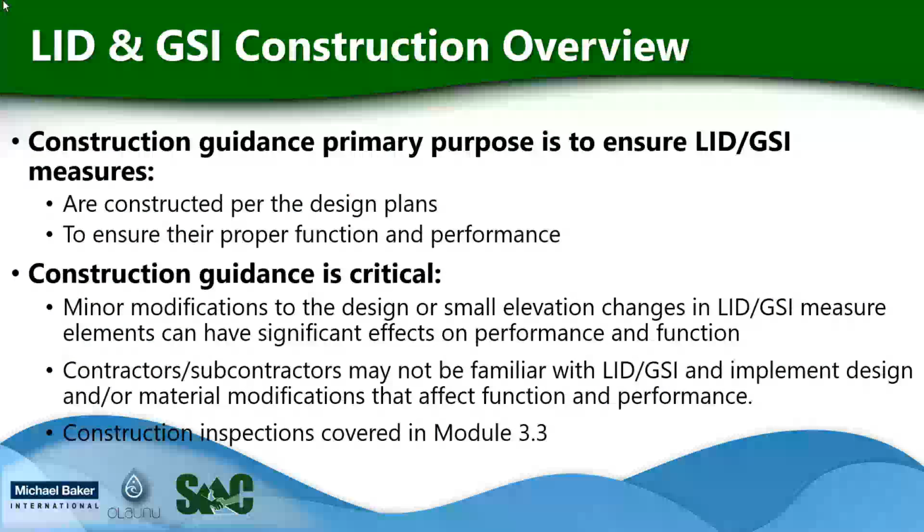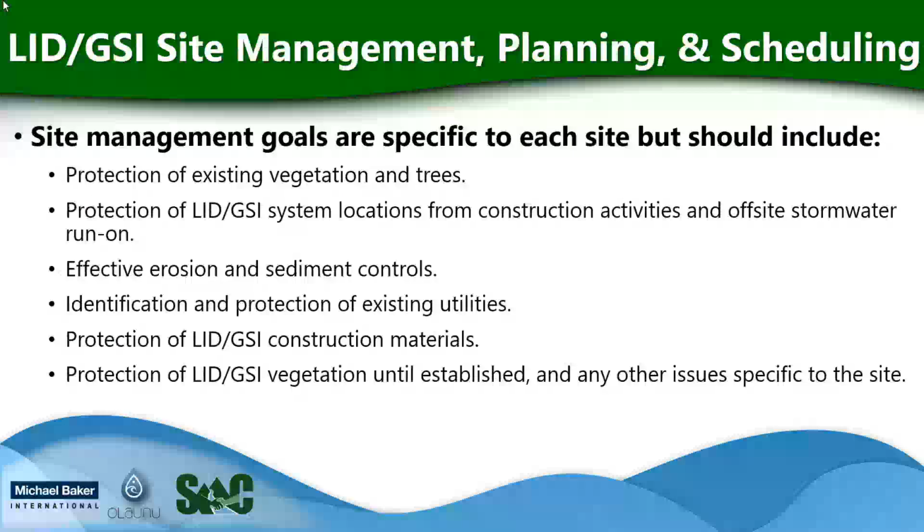One of the critical elements to construction guidance for LID and GSI systems is site management, planning, and scheduling. The development of site management goals is an essential step in the planning of an LID or GSI site. The site management goals and the construction sequencing schedule should be developed prior to the pre-construction coordination meetings with a contractor and subcontractor.